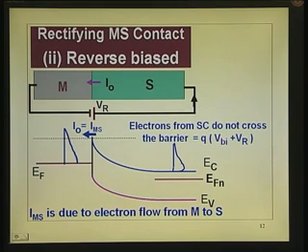Okay. Now, let us see what happens. And this barrier, you see how much it is depends on phi BI plus VR. phi BI was just enough to compensate for I naught. Once we have put VR sufficiently large, I naught is not compensated at all. You have the net current flowing through that.